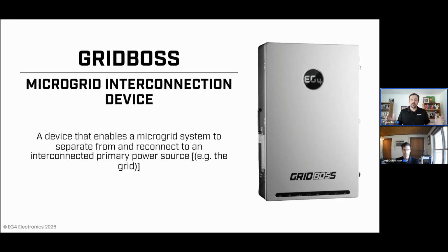You've heard me refer to it a couple times now as our microgrid interconnection device. You'll also hear us say MID, which is just an acronym standing for microgrid interconnection device. But what that is defined as per the NEC is a device that enables a microgrid system to separate from and reconnect to an interconnected primary power source, e.g. the grid in most instances. Now, what that means in more practical terms is the MID is simply a relay that will open or close under the appropriate conditions to adhere to the relevant grid interconnection standards and requirements.